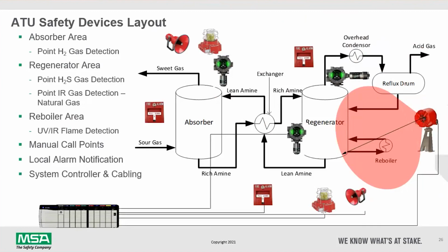Wanted to show you that, of course, all these I/O devices need to be wired into our logic solver. And just for clarity, I did not show the cable routing up to our upper level devices on our slide, but you get the idea that everything needs to be routed back to input cards and output cards as required, again, for our logic solver to do its job and continually scan and update as required. And then don't forget, our technicians in our case study are fitted with portable gas detectors to enable them to detect on their person any of the hazard gases we have present in our ATU area.